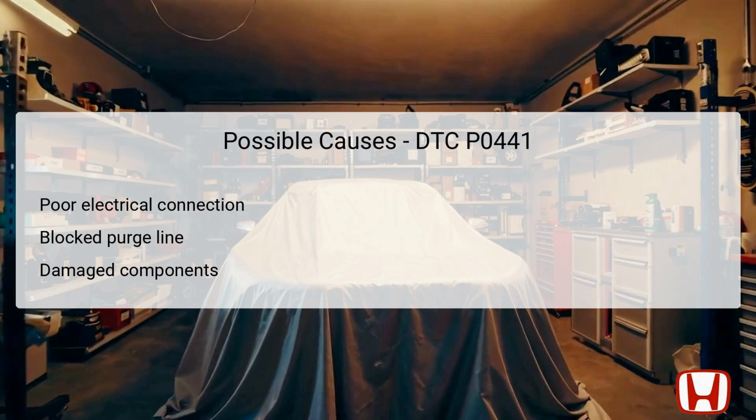Therefore, a thorough inspection of these components is essential. If any of these issues are discovered, rectifying them promptly will assist in resolving the DTC P0441 and restoring proper EVAP function.